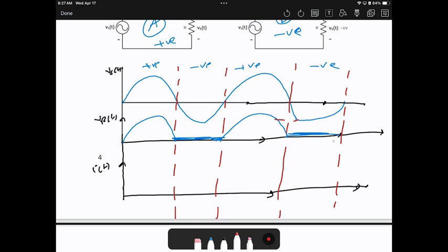Okay, so the values here, when it is at the negative, are bounded between negative 10 to 10. Then here are the diodes or rectifiers. This is at 10 volts. Okay? So the source is between negative 10 to 10, and here the peak is 10. So look at Vs and Vr: only the positive part will pass, while the negative part will be blocked. This is because of the diodes.